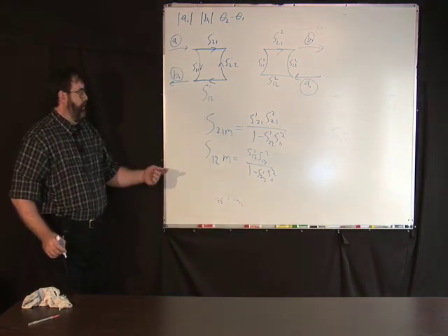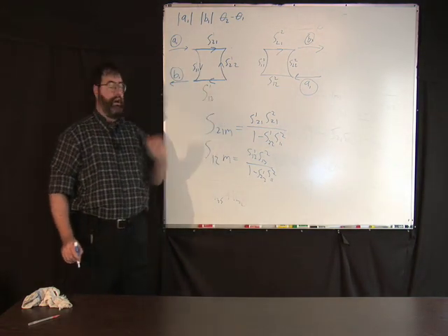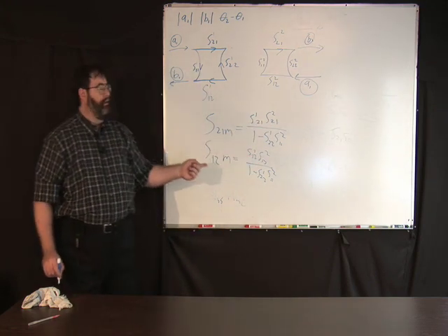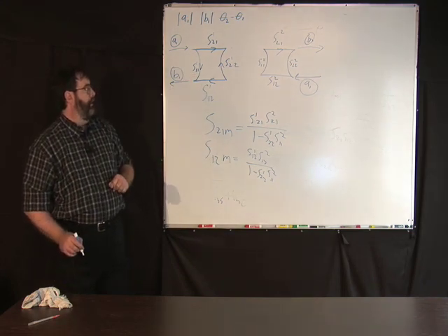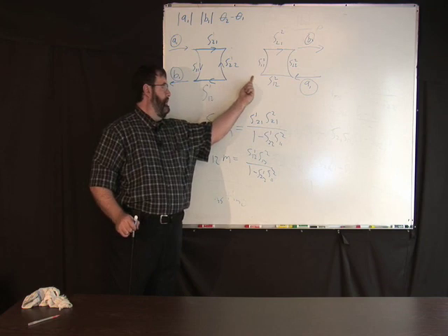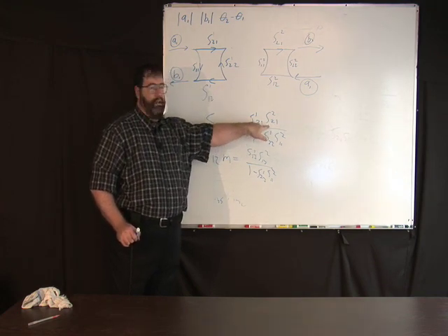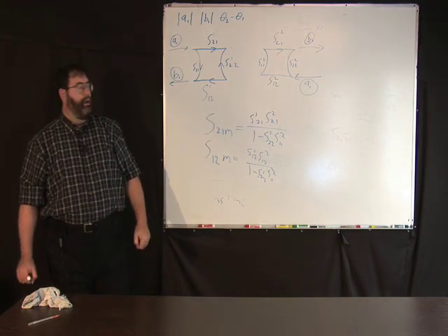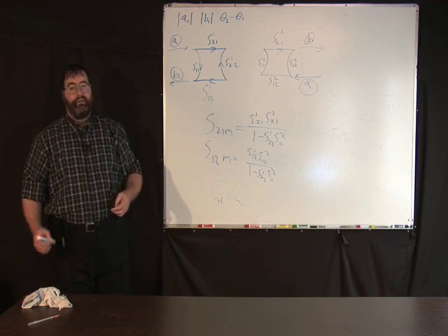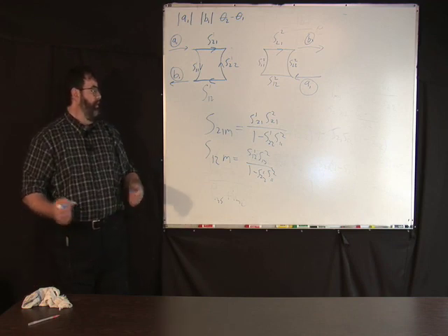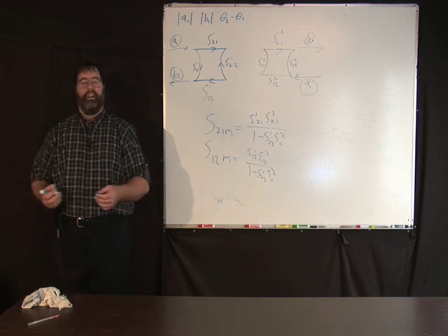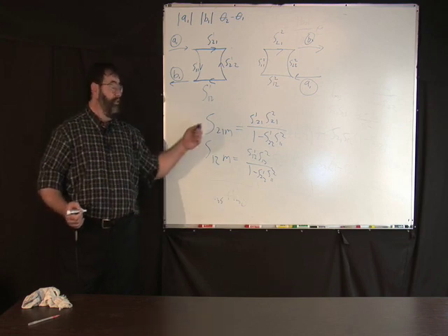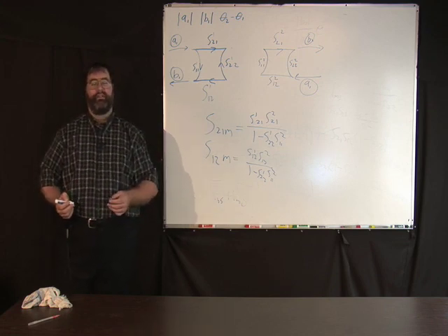Well, you know this from calibrating each side as a one-port, so you can solve for what these combinations are. But whenever you're measuring an actual device, whatever you stick in here, this combination will always appear and this combination will always appear. So once you know this value, you can stick it into the equations for calibrating out a two-port. So there you have it in a nutshell. Calibration of a one-port reflectometer or a calibration of a two-port network analyzer. In this case, a vector network analyzer, because we did everything complex.